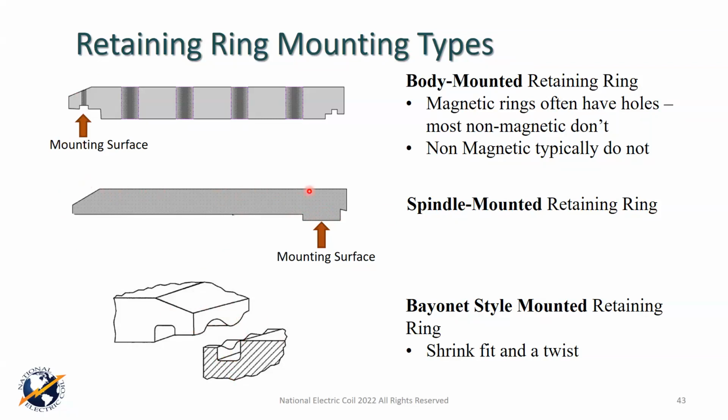And so you would heat up the rotor and try to keep your heat fairly consistent with an emphasis on this area, and they should be monitoring the consistency of it and the temperature with a pyrometer. And there are thresholds on temperature you want to maintain and not exceed, so you don't mess with the metallurgical characteristics of the ring. But once you establish that differential between the ring temperature and the rotor forging surface temperature, you have lifting devices, and they slide it right off of the fit, and it should happen fairly easily, okay?